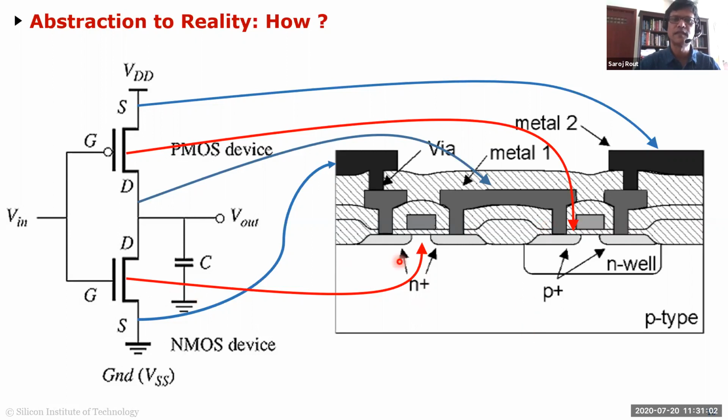So for example, this NMOS has a source area, drain area, some oxide, a gate here. There's some metal connection going from the NMOS to the PMOS, which is sitting on an N well, some source and drain, gates, and so on. You connect one level of metal, then you connect another level of metal, and between metals, there is all this oxide, which is basically glass, which is an insulator, so that you don't short these 2 metal layers, because it's kind of a 3D stack of metal. So it's like a PCB where you're using different layers, and you have FR4 board in between the metal layers so that they don't short. Here, instead of FR4, you have silicon dioxide, basically.